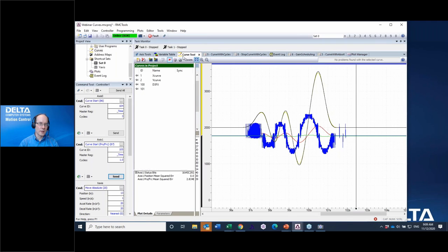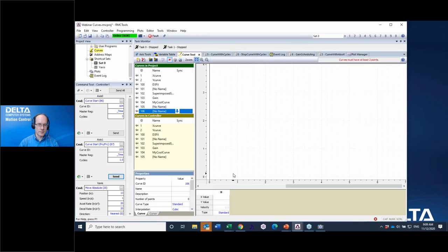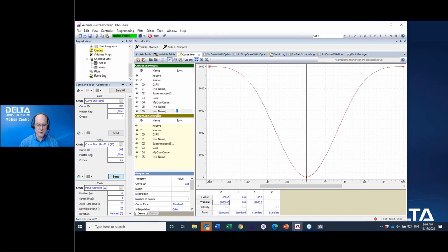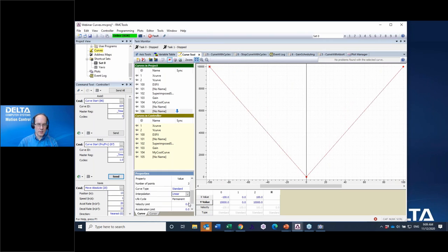We can actually go and create a curve like that if we want to. Let's see here, we'll do 0 and 0, and we'll say maybe a position of 100 inches. You want, say, I don't know, 10,000 pounds or something. And minus 100 inches, you would use 10,000 pounds. And we would have to do that linear, of course, not cubic, if we want it to look like we want. And so we could send this command for a force curve while we're in force limit and also be doing position control. In fact, if you really want to confuse yourself, you can do a curve on position while you're doing a curve on force limit. It gets really interesting sometimes.